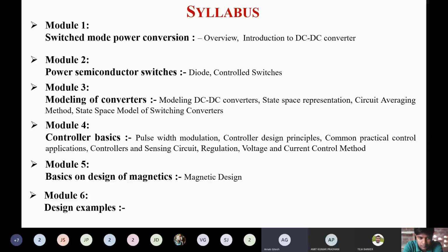Okay, so how do you realize it? The output voltage is high, comparatively bigger than your fixed value of voltage, so that causes a positive error. To get the error you use a differential amplifier. In the differential amplifier, one input is coming from your reference signal and the other input is coming from your measured signal. So from the differential amplifier you are able to measure that error.